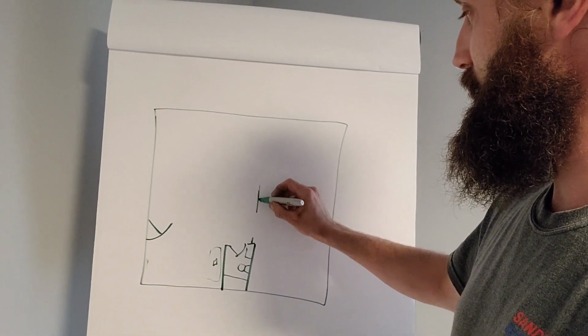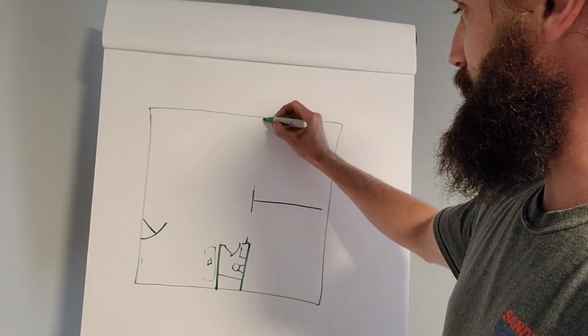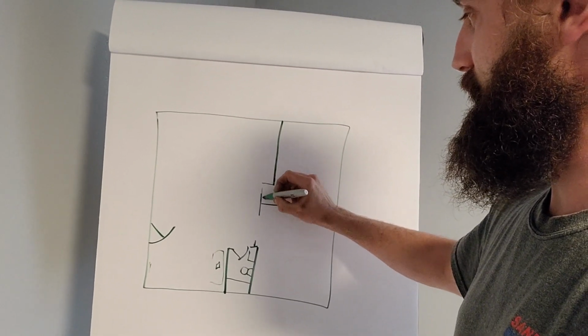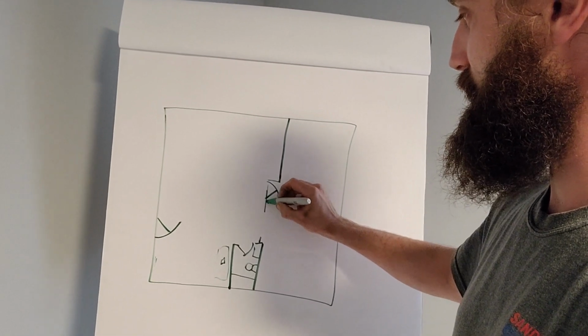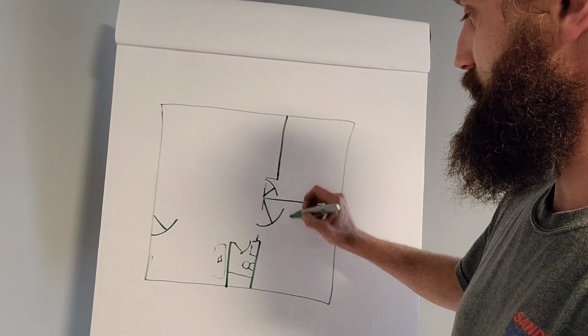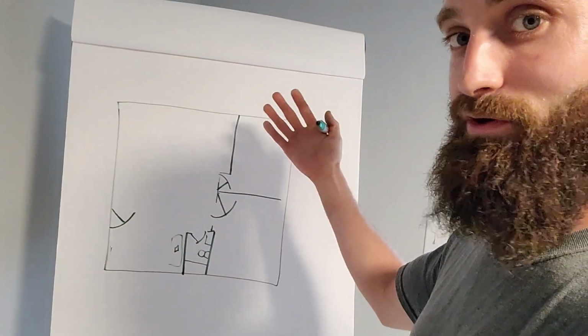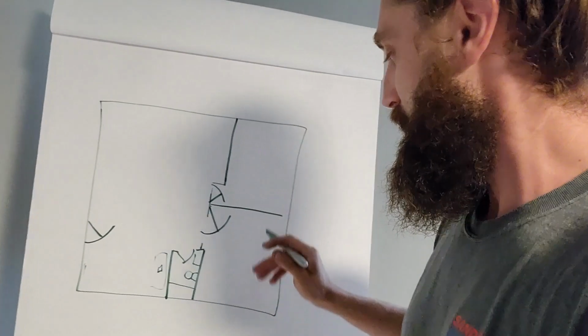If we've got a china hutch, same thing. A couch, you kind of know where things are going to end up. So I will jot those in my notes so that whenever we're doing our duct sizing, I know where I can and cannot put specific supply and return registers.